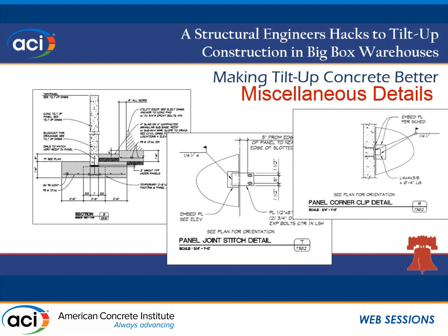Cantilever connection, use temporary footings, space periodically, and then cast the bottom of the panel in. Hey, the panel doesn't care. It's a retaining wall. It's going to do what it's going to do. And then when you have one of those bearing type connections, don't forget to put some details in there to hold the panels to each other to make sure you've got an out of plane load path.